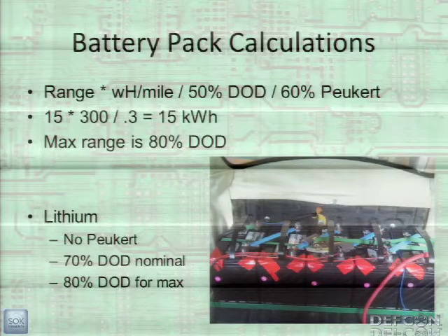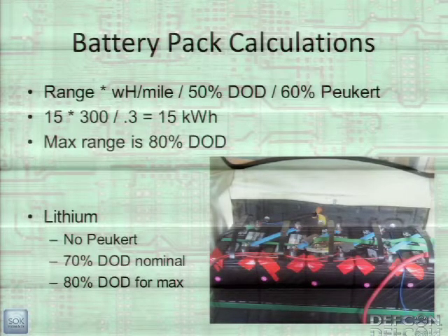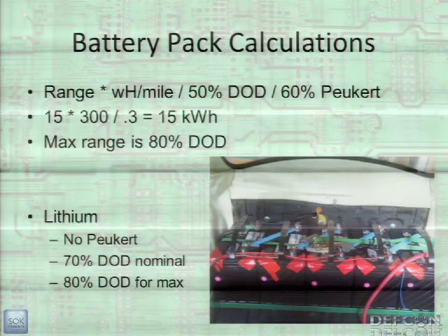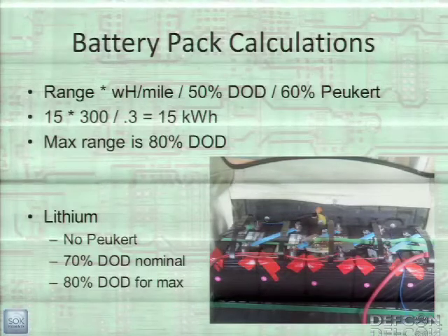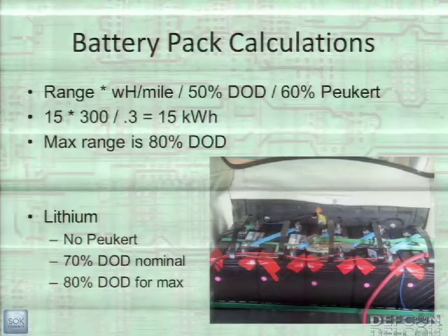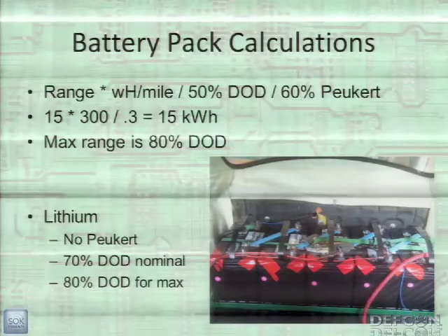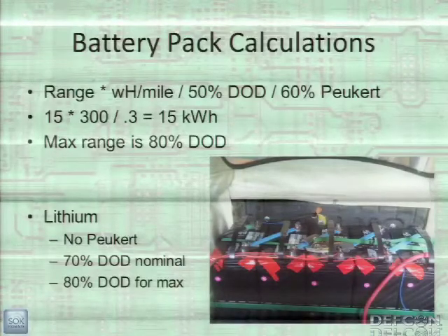And there's something called the Peukert effect. Every battery has a sticker rating, and that sticker rating is if you take 20 hours to drain that battery, that's how much power you get out of it. Obviously in a car, you're not going to spend 20 hours draining the battery. You're draining in about 1 hour, maybe half an hour, so you can't get nearly as much.